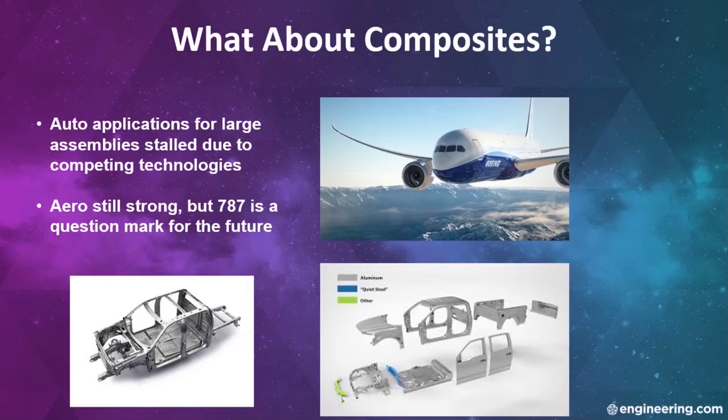It's a lot. Ford's 5-year billion-dollar project, the Novelis application-specific aluminum alloy for the F-150 program, that's pictured at the bottom, well, that's been an engineering and marketing success, and competitors are now using substantial amounts of aluminum in cab and box construction. And by introducing this first in pickups, Ford engineers still have that advantage of that ladder frame, removing much of the load path management duties of the body assemblies. Compared to two lightweight formable metals in steel and aluminum with wide commercial availability, we expect composites are going to stay small in automotive despite advances in automotive layout.